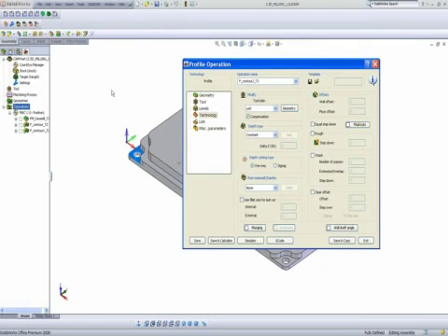Now, by using an 8mm tool, although it's good for this particular corner over here, it may not cover this entire area over here. So again, when I do my rough and finish, I will again use a clear offset. Now my wall offset, I'll leave 0.3mm for the finish. And my clear offset, I'll say, okay, let's start 5mm away, go in a total of 4.7mm.